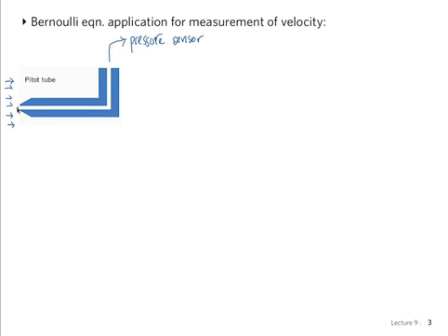We can say 0 here because all of the fluid inside the tube we can consider to be 0. And so this is a stagnation point, and therefore the velocity equals 0 there. And so we get stagnation pressure, basically the same situation we had before.